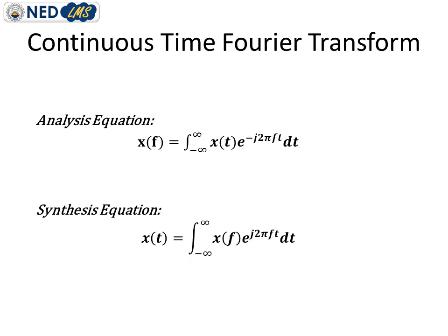Yes, this technique can be useful if you already have a signal, a recorded one or one provided to you on paper, and it will be continuous and aperiodic in shape. So yes, you can apply these equations, and you will get the result, and that result will be equally valid. But you cannot process any real world signal with the help of this continuous time Fourier transform.